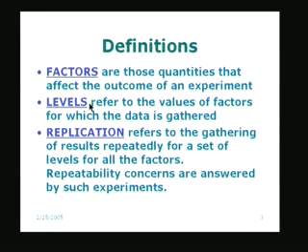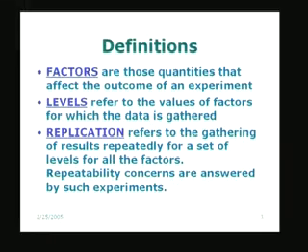So the levels we are talking about here are the values the factors will take in the experiment. I may have a lower limit for the factor, and I may have a higher limit for the factor, and in conducting an experiment I may set these at different values. Each value which I am going to use between the maximum and the minimum becomes a level. For example, the speed may be varied from a low value of, let us say, 1000 rpm to a higher value of, let us say, 3000 rpm, in terms of revolutions per minute.